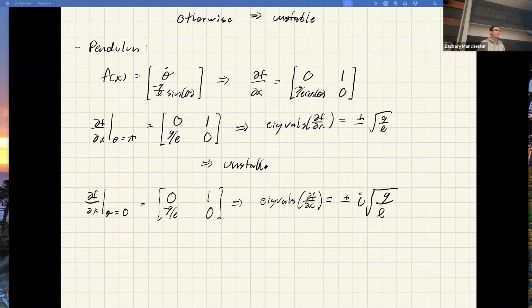So yeah, what you got? That's exactly right. So remember, intuitively from a dynamics perspective, the real parts correspond to damping. So if we have a purely undamped system, that means it's going to oscillate forever. So you have real parts damping, imaginary parts oscillation, right? It's complex, it's Euler's form, it's a complex exponential, so the imaginary part is sines and cosines. So this is just saying that this thing has undamped oscillations, and the frequency of oscillation is square root of g over L, which if you remember your freshman physics, is the oscillatory frequency of a pendulum, right? So that all checks out. This thing oscillates at that frequency forever with no damping, which intuitively makes sense.